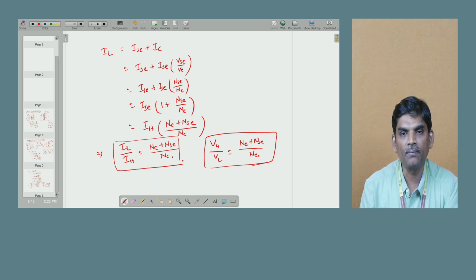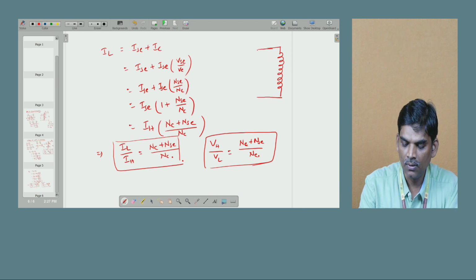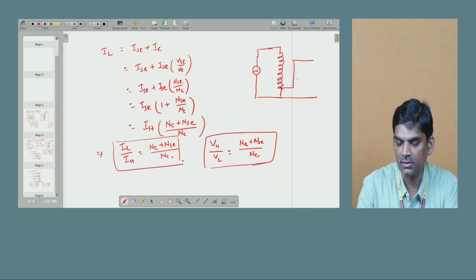Another important point in an autotransformer is that the per turn voltage is the same. We can take it as a single value: per turn voltage is the same. So how much it is variably operated? We are considering from 0 voltage to 120% of rating, we have to change it, right? Per turn voltage on both sides is the same. That's why the number of turns is increased, so automatically the output side voltage is varied in this manner. This is also an autotransformer.